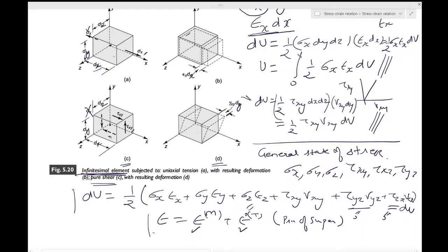On the other hand, this addition which you are doing now is not due to the principle of superposition, because if the stress is linearly proportional to the strain, this is actually a quadratic function in strain. So this will be essentially epsilon x squared divided by the constant. So you cannot add quantities which are quadratic. That is not the principle of superposition. The reason you are able to apply this concept of adding is the same idea which you have done before.